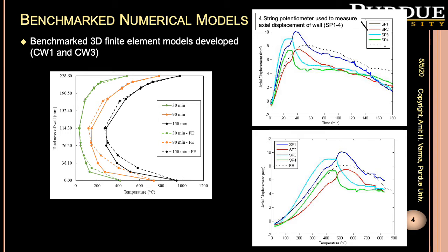In the test, to pass the thermocouples through the steel faceplate, a small hole was provided in the faceplate. So during the fire test, water was escaping from the hole. So the water migration wasn't simulated in the models, and this caused a difference in the measured and estimated temperatures within the wall thickness at areas close to the hole in the faceplate.